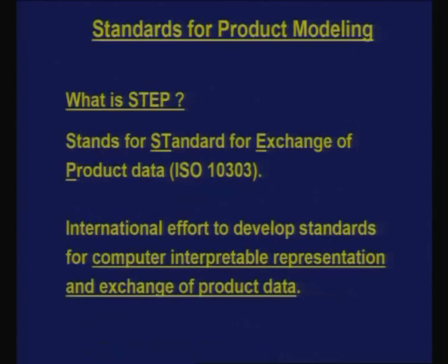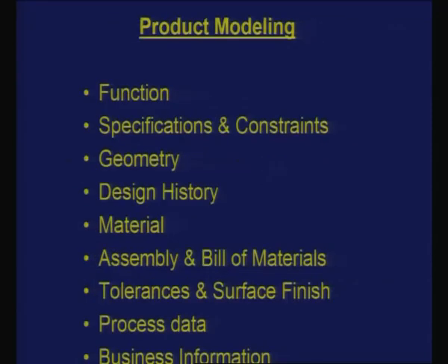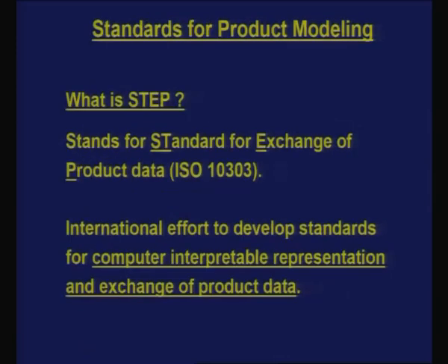And one international effort, an international standard which has been developed to take care of most of this data exchange, not geometric data exchange, but product data exchange, is what is called STEP. STEP is again an initiative of many countries, European, US, Japanese and many others, and primarily an initiative of the US National Bureau of Standards, and it has an ISO number 10303.